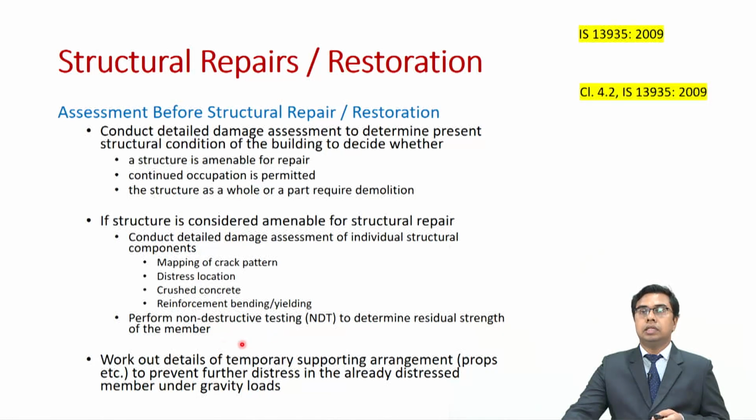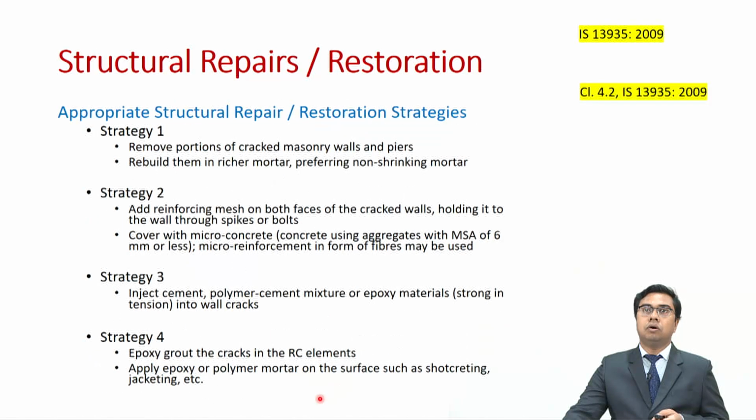Now, after doing this, we shall work out the details of the temporary supporting arrangement, that is, props. These props will help us to prevent further distress in the already distressed member under the gravity loads. So, that is how the props are important, so that there is no further distress in the distressed member while we are conducting our structural repair or restoration. After we are done with all this assessment, now we can get to the structural repair or restoration.